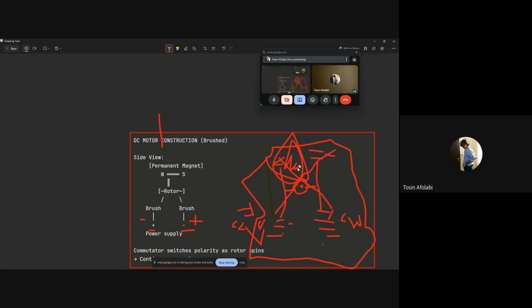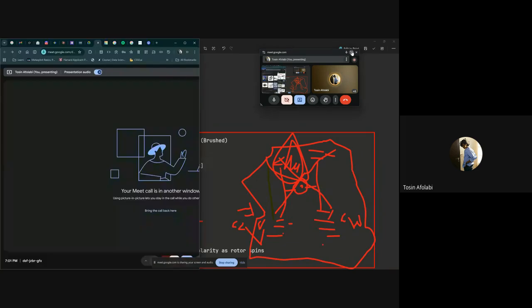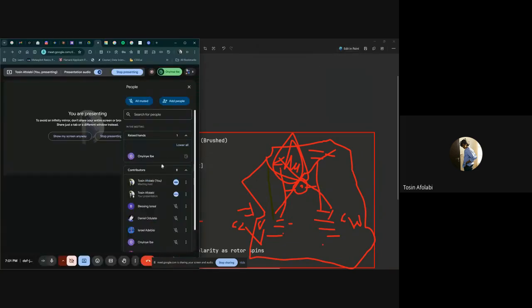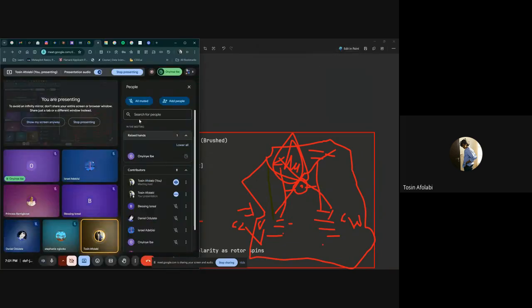Now, the reason why we are using this entire H bridge in the first place is what I was explaining: the things the Arduino pins cannot do. They cannot provide enough current for the motor to run, and they cannot reverse polarity.